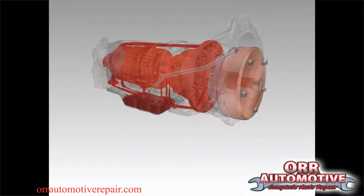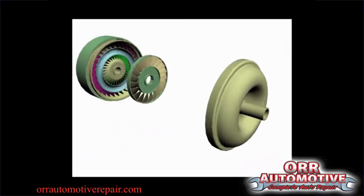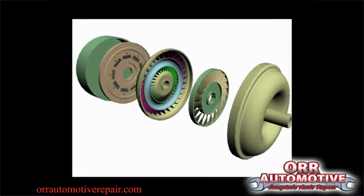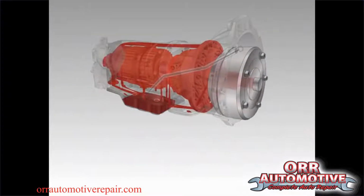The transmission fluid keeps moving parts inside the transmission lubricated and cooled. The torque converter is a fluid coupling that connects the engine to the transmission. At slow engine speeds, the torque converter slips to allow the engine to continue running even when the vehicle is stopped. As engine speed increases, the torque converter transfers power to the transmission.